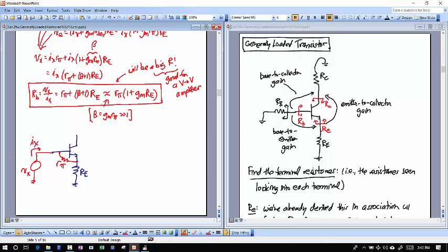Because I don't need the hybrid pi model for me to know that if I have a base current here, IB, which is going to be equal to Ix, and my collector current I can write as beta times IB. Right? You know that. And you know by KCL the current running through this RE is beta plus 1 times that IB. Okay?